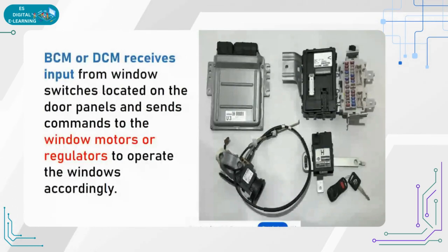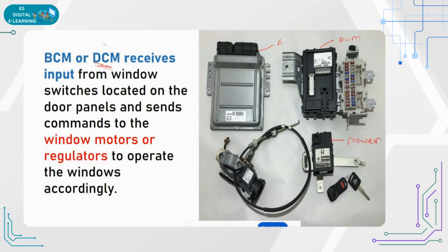In some of the major cars, it is separate. The door control module has a separate unit, that is the DCM. It can be a part of the body control module or a part of a DCM. These ECUs also handle the power window, and can be accessed with the remote lock key. So these are some ECUs which we are using in cars. These are a part of microcontrollers, because internally it has two or three controllers in it, enclosed in metal, and placed in the cars.